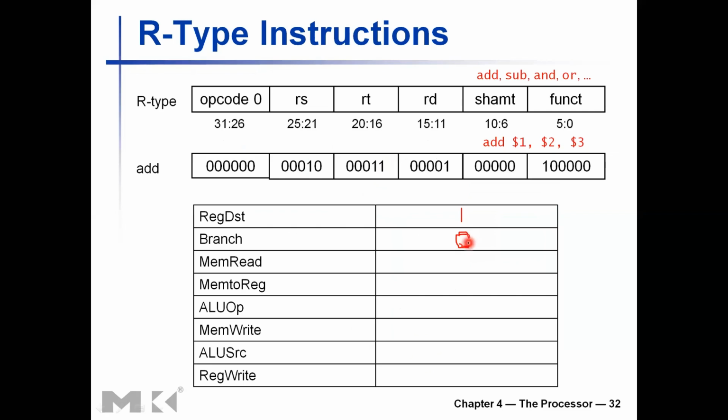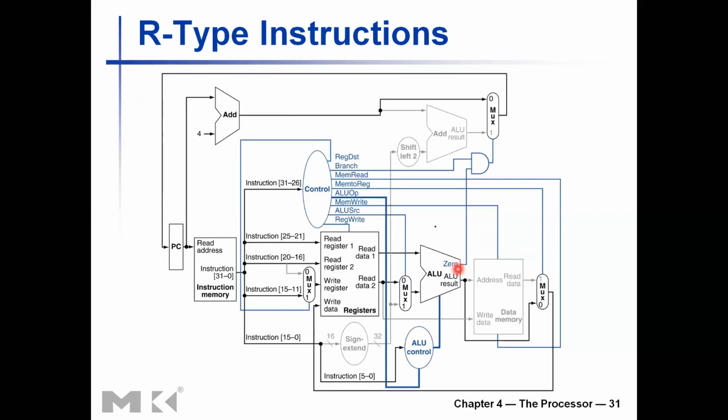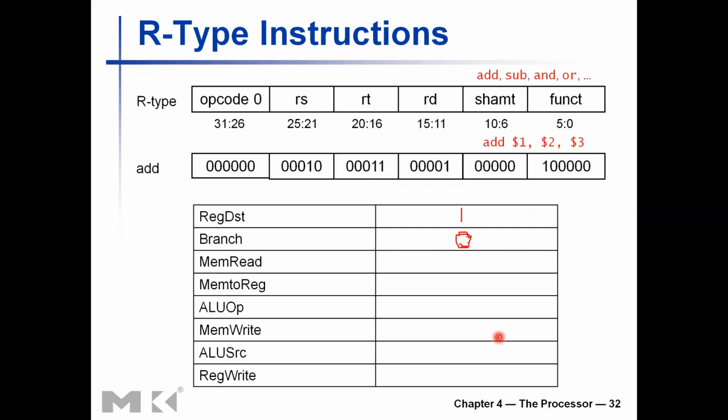That should be 0. Right. Okay, finally. So next, mem read control signal. What does it do? Mem read control signal is sent to the data memory device to read from that. We only need that for a load word instruction when we read from the memory. So here that is a read control signal. We don't read from the memory, so that value also should be 0.